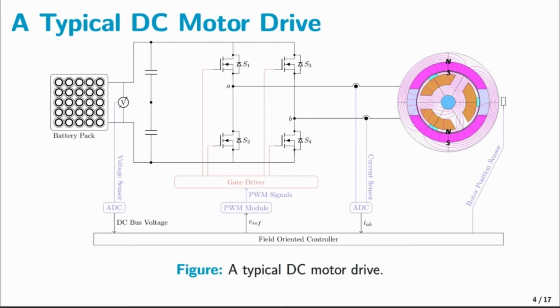By combining multiple half bridges, we can realize a wide range of power converter topologies, from simple buck and boost converters to more complex structures such as LLC resonant converters, dual active bridges, and three phase two level converters. Hence, understanding the design aspects of a single half bridge is critical.